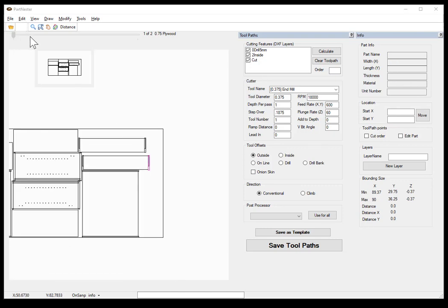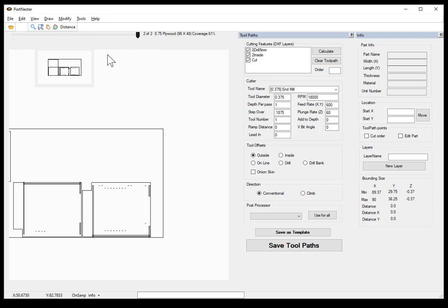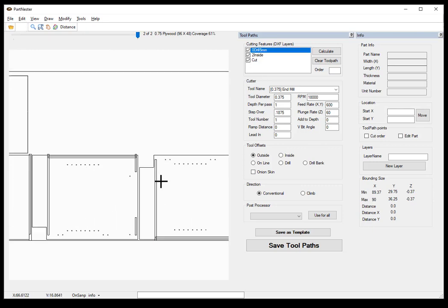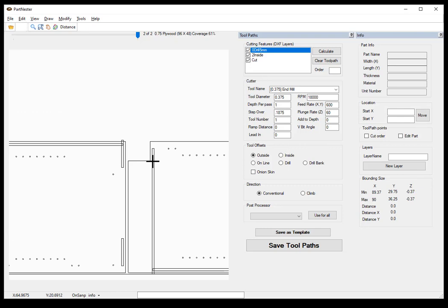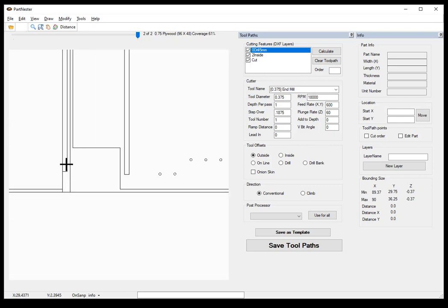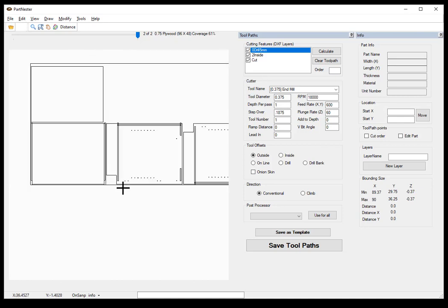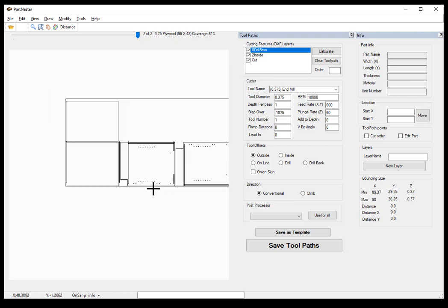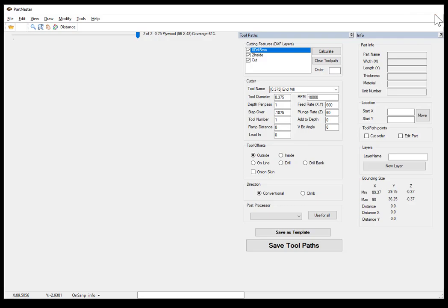If we scroll to sheet number 2, we will see that the base cabinet sides have the dado that is still set to have the stop at 1.5 inches, 3/8 wide dado to receive the rabbeted bottom sides to fit. So again, we could just go ahead and make the changes for that base cabinet just the same way that we did for that wall cabinet, and also for any other cabinet type that is in that list. All work the same way.